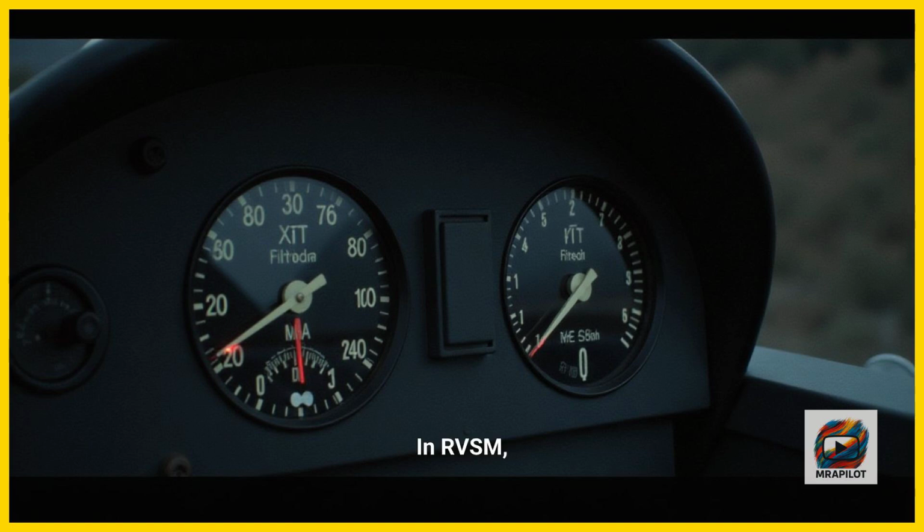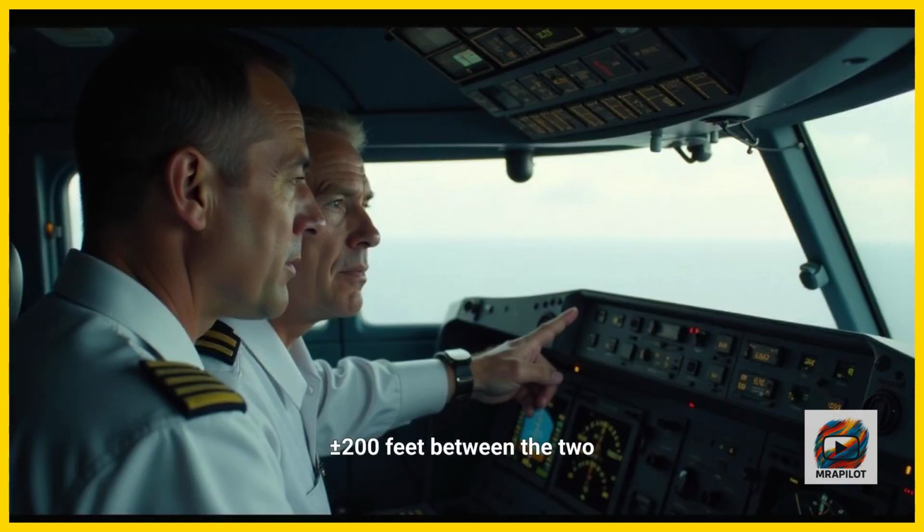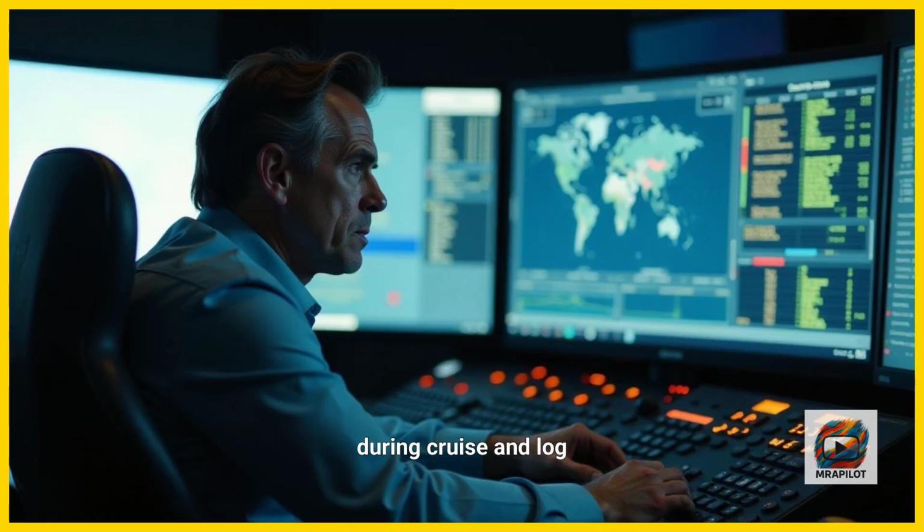In RVSM, allowable altimeter error is usually plus or minus 200 feet between the two systems. Pilots must monitor both altimeters during cruise and log discrepancies. If the difference exceeds limits, ATC must be informed and vertical separation increased.